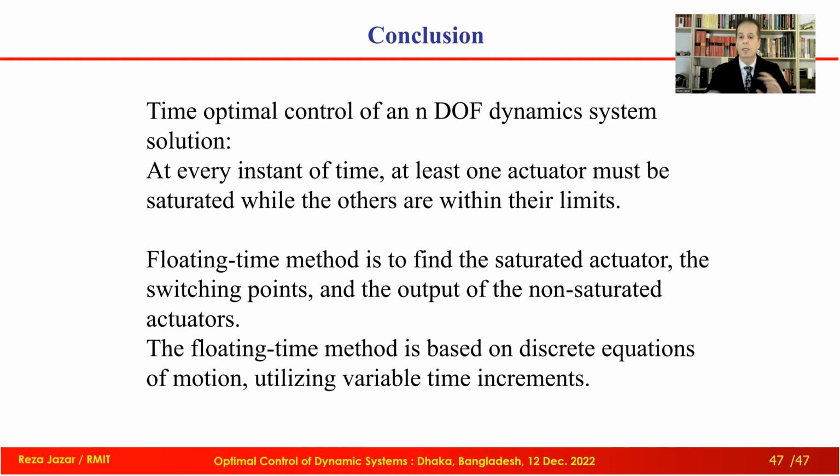It works very well. And when we solve this problem for a robot, what is the solution? The solution is that we derive the curve or the value of motors or actuators at any time. Then we dictate those values by computer to the actuator, and the robot moves from the beginning to the end according to minimum time. Well, this was a very simple explanation.